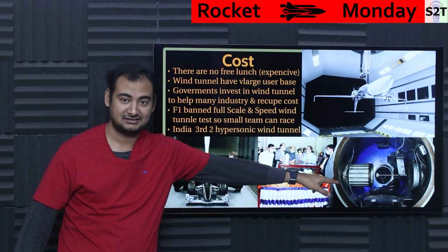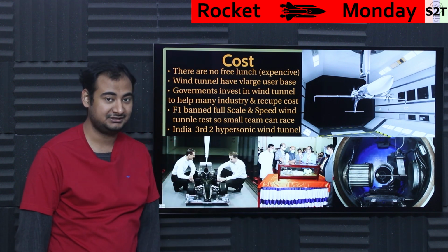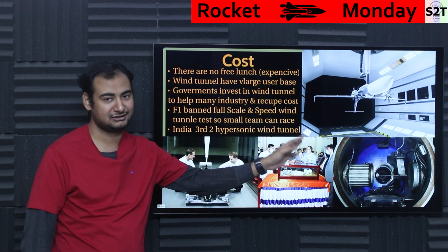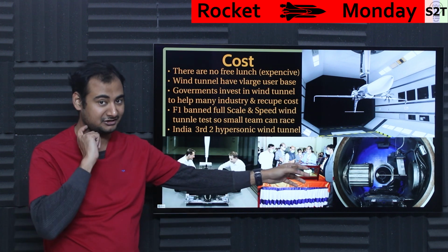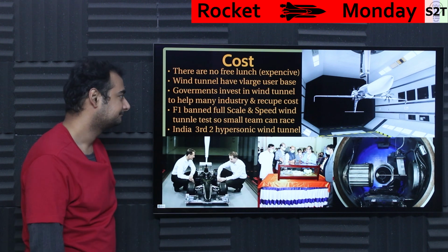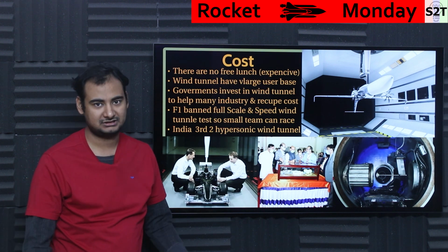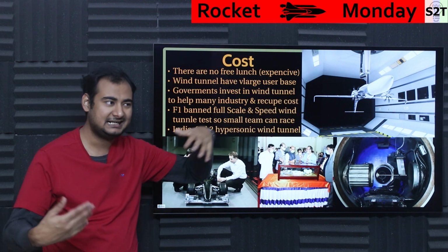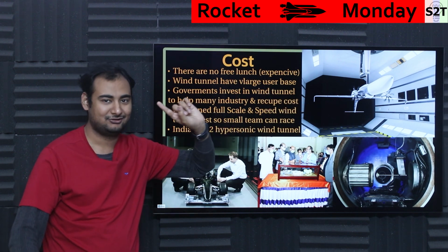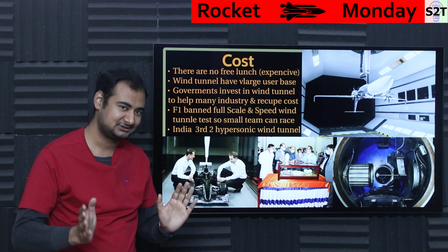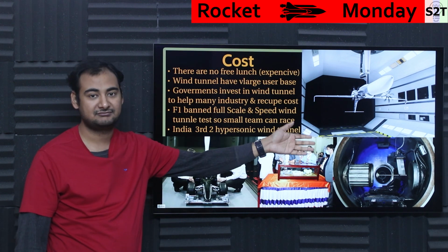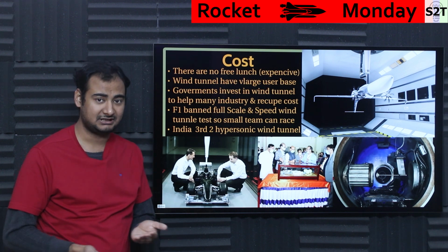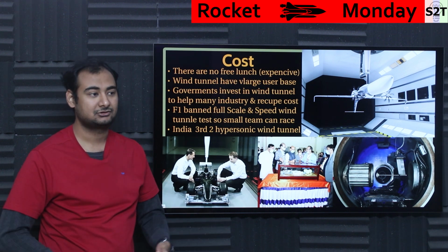So whenever you see NASA able to test something in hypersonic, be mindful, that's a very big deal. And that means they have very solid confidence in the model. Otherwise, they're not going to waste hypersonic wind tunnel time. That's very expensive. And again, if you are a jumbo jet company, then you're going to have a transonic wind tunnel of your own. That you can afford, but be mindful, a small one. Not where you can put very large models, small ones. But these things are generally designed for continuous running because that also gives them fatigue characteristics. So that's the cost. That's why generally governments build this and they rent it out to different branches.